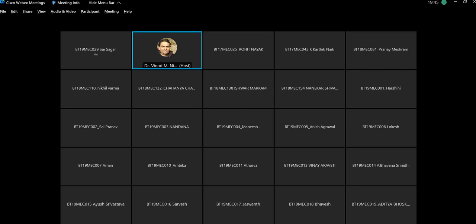So in fatigue loading, a cyclic load is repeatedly applied on the specimen, and the material can fail below the yield strength also. That stress level is called the endurance limit of the material. So all these concepts we will see in today's lab.